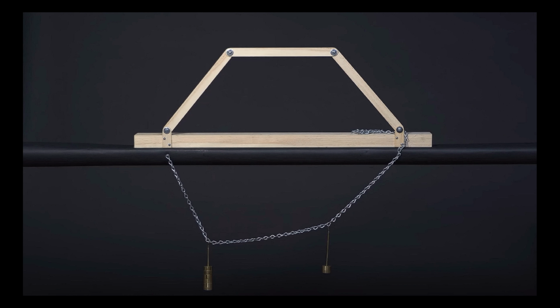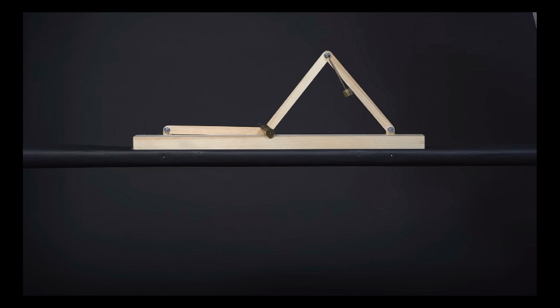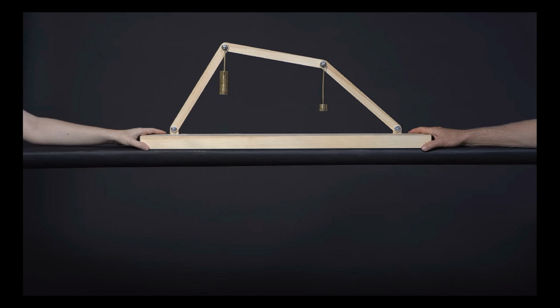Chains are tension systems, so they automatically reshape to better carry whatever load is applied. Because arches are compression systems, they do the opposite. If they are not shaped appropriately for the loads they are asked to carry, they can collapse. In our project, this results in unbalanced stress distribution, which increases maximum deflection. If they are shaped properly, they give the best results.